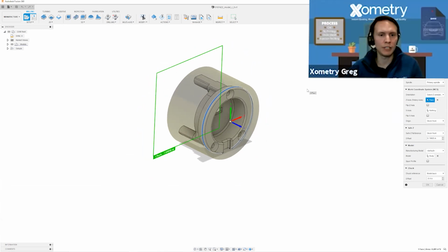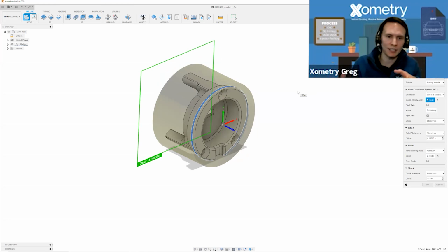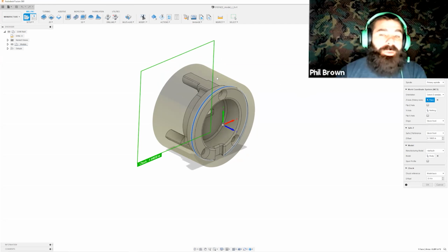So when you change the coordinates for how you're oriented in your machine designs and the manufacturing, it's not going to change how it's oriented within its assembly or anything upstream in the design process. Correct. I'm leaving the part exactly where it is. I'm just defining my G54 offset, or whatever you use for work offset, without modifying its current location. Awesome, very fast. And the nice thing about this is I'll be able to do multiple operations in one file, keeping everything uniform and together.